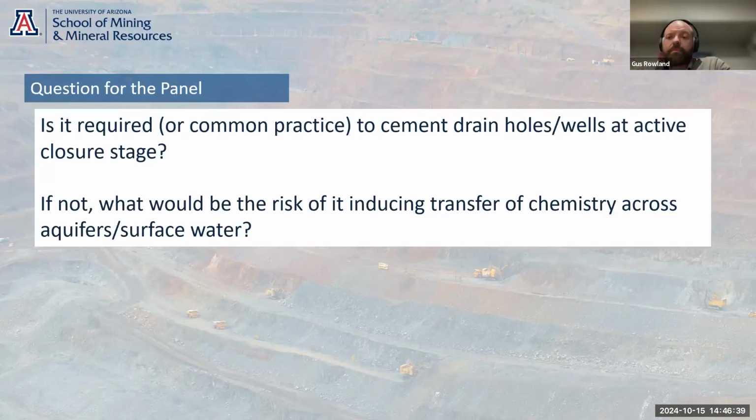Good question. I think I'll give a quick comment there. I think the most common implication of not cementing exploration holes is certainly if you decide to build an underground mine in future, you risk inducing flow to your underground operation. This is something that's quite common in Southern Africa with underground mines that are being planned and excavated beneath old open pits that were never envisaged. And so you're getting a lot of intersection of underground, open exploration holes that bring flow through from shallow aquifers through to the underground operation.